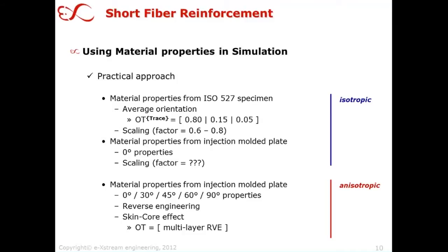And what you can do also, of course, is you take all the measurements from the injection molded plate. So you have experimentally measured your anisotropy, your dependency on the angle with respect to the fibers. And now on all the curves you have measured, you perform some reverse engineering of some anisotropic material model, and even here you can include the skin-core effect, as we have discussed it before, in terms of putting up a real multi-layer RVE. So RVE stands for representative volume element.